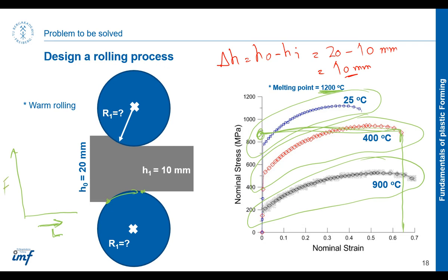So basically what is always happening is that this force is less here, increases, and then falls back at this point, and this point is usually the neutral point, or the point where the force is maximum. This is where the speed of the roller is equal to the speed of the billet, and where there is only one component acting on the billet rather than two components, horizontal and vertical, and therefore the force is highest at this point.